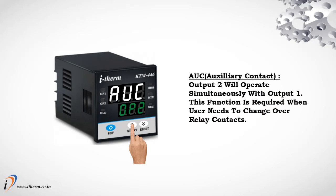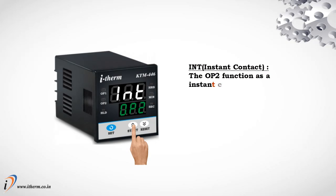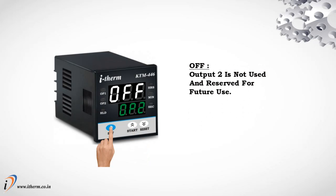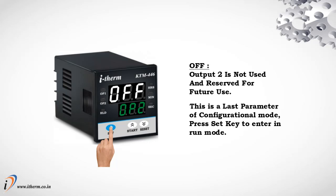This function is required when user needs to change over relay contacts. Instant contact. The output 2 functions as an instant contact which operates immediately when timer starts and remains in that state till the start of next cycle. Off. Output 2 is not used and reserved for future use. This is the last parameter of configurational mode. Press set key to enter in run mode.